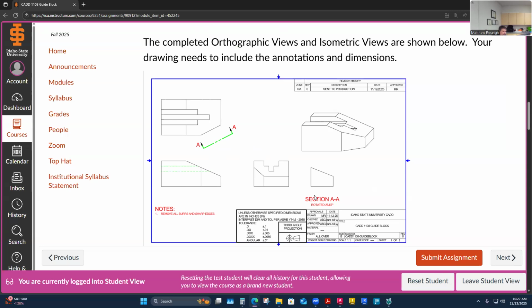Maybe so. I don't know. It's just one more exercise, one more thing to add there, since we know it would be foreshortened. It's foreshortened there. It's foreshortened there. It's only top down there. So technically, I could make an argument that I should detail this view, this surface. Then we just start to say, yeah, I probably should. This is foreshortened. This is foreshortened. Why don't I pull an auxiliary view of this? Yeah, it's a good argument. I could. We don't have to, but it's only showing its true length here.